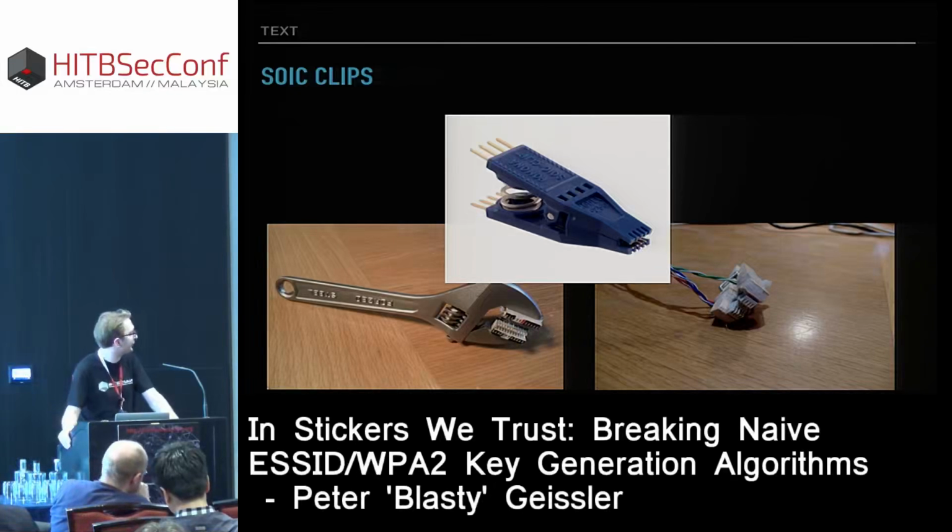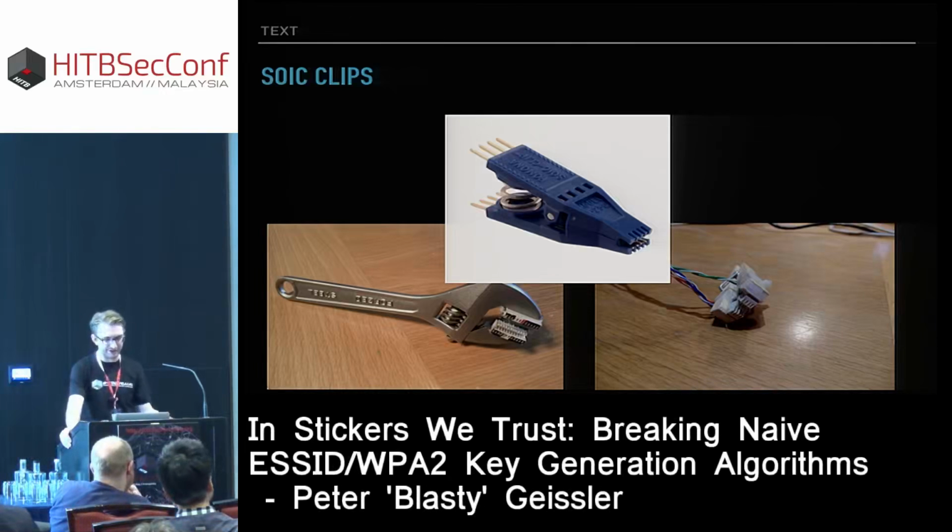Before I started soldering to the flash chip, I was talking to some friends. I didn't necessarily want to avoid the soldering. Soldering isn't too bad. It's SOIC, so the pins aren't that tiny. You don't really need an SMD soldering station or anything. You don't need super advanced hardware. But I was looking into avoiding soldering. So I found out about these clips. They apparently work really well.